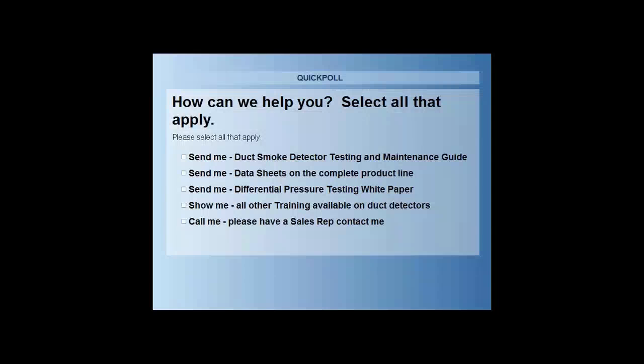If you are using a DNR intelligent duct smoke detector housing, on the power side there is space located on that section for an intelligent module to be installed in the housing. The module does have to be purchased separately, but there's space for it in the housing. Once you have that installed, you can use that for shutdown.